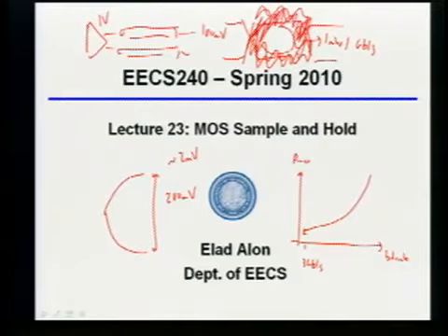For the offsets, you wanted us to compute the offsets for everything, right? So that's including like the transmitter if we change it. That's right. So basically everything that has a MOSFET associated with it has an offset in it. So even though I gave you, for example, like the CML comparator and the transmitter and things like that, you have to include all the offsets inside of those blocks as well. Sorry, they have offset too. They're real circuits.